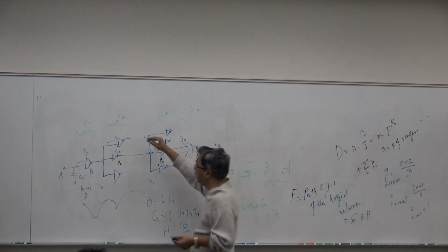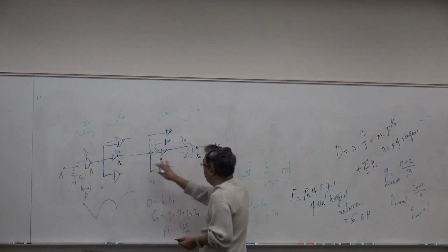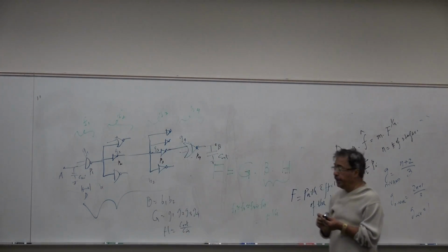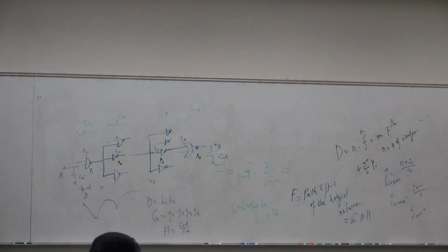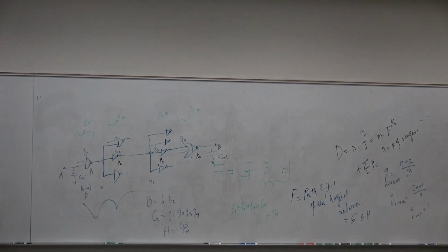We are not interested in this or the other one. On the path of the signal, whatever the gates are, they have parasitic delay. The sum of that, we put that. So this is how we calculate the delay.